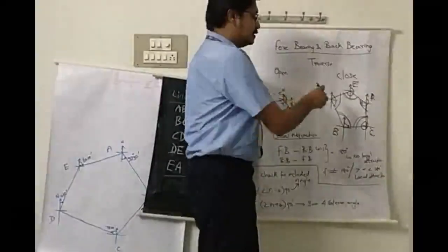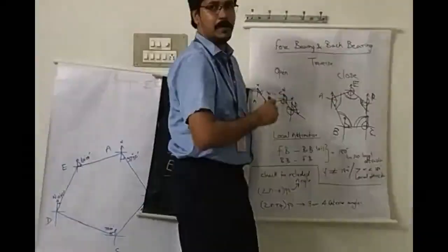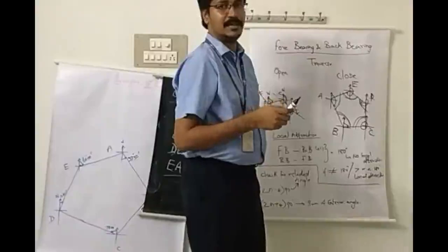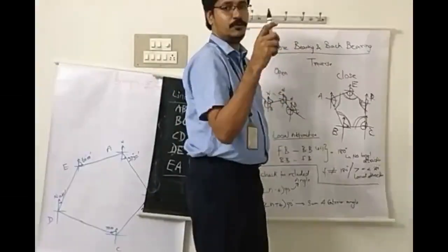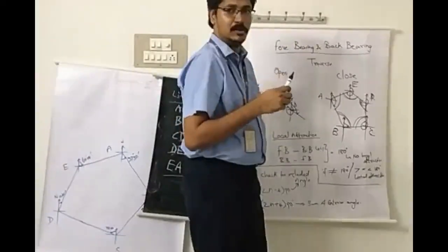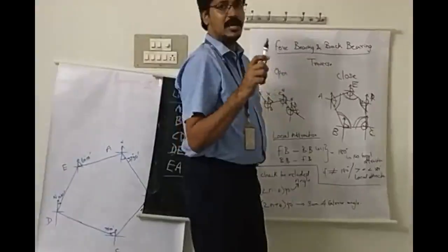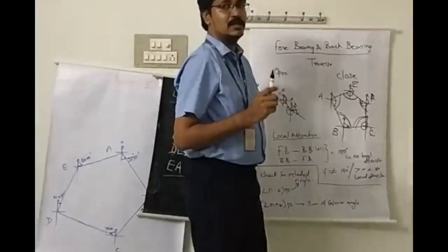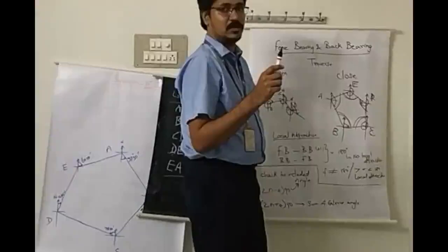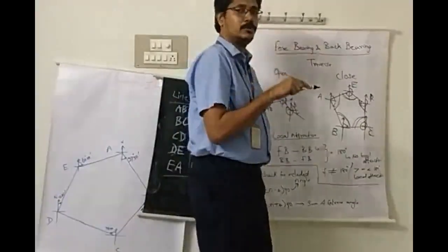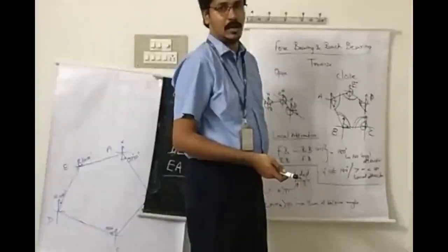Otherwise, by the standard readings, what we have obtained as the fore bearing and back bearing in the field, if you make the tabulation and check the fore bearing minus back bearing in all the lines, if there is any deviation in any line, then we can find there is a change. That correction can be applied to the bearing, then we can calculate the included angle, right?